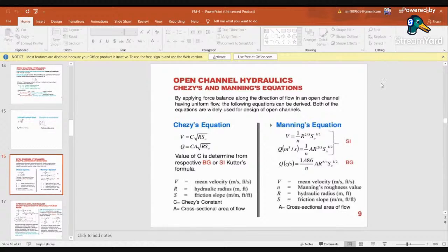Then there is one more equation, that is Manning's equation. Manning's equation is V is equal to 1 by n R to the power 2 by 3 S to the power 1 by 2. Again, the modified equation for Manning's equation will be Q is equal to 1 by n A into R to the power 2 by 3 S to the power 1 by 2. Okay, again here V is velocity, n is Manning's roughness constant, R is the hydraulic radius, S is the frictional slope, and A is the cross-sectional area.